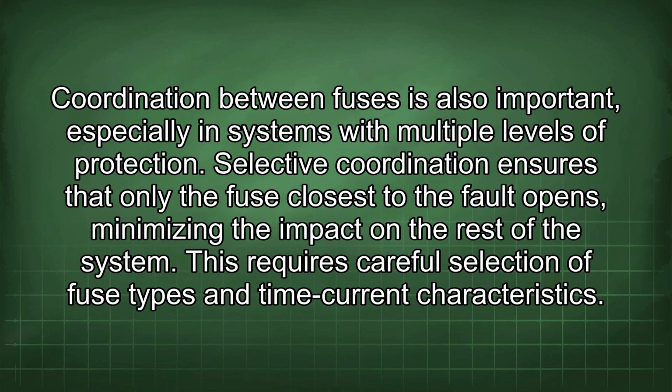Coordination between fuses is also important, especially in systems with multiple levels of protection. Selective coordination ensures that only the fuse closest to the fault opens, minimizing the impact on the rest of the system. This requires careful selection of fuse types and time current characteristics.